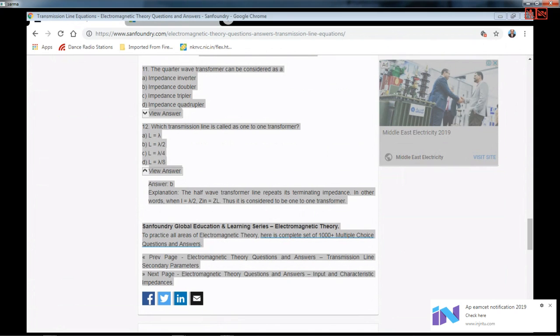If ZL minus Z naught is going to be finite, if there is any difference between ZL and Z naught values in terms of real and imaginary components, then there is going to be some unwanted return signal which is having some relation with the input signal through capital gamma. So capital gamma is the way we try to look at how much unwanted thing is happening on a transmission line. So capital gamma is defined as V0 minus by V0 plus.